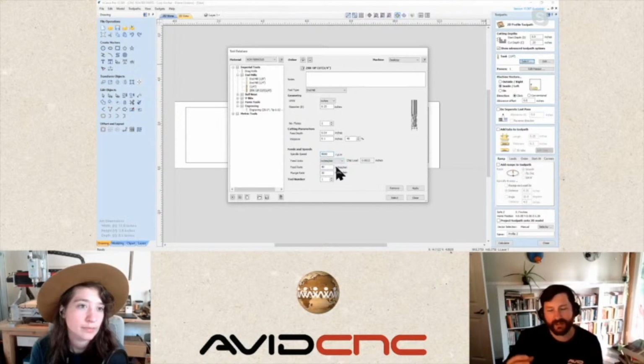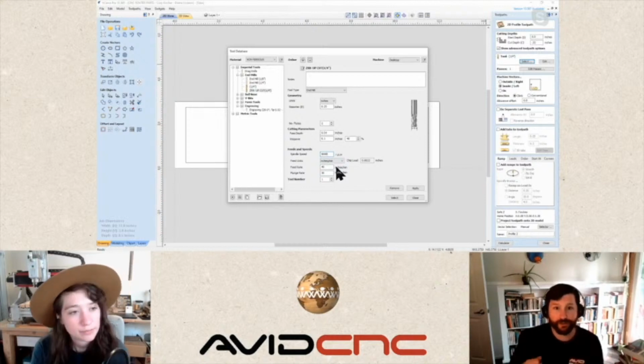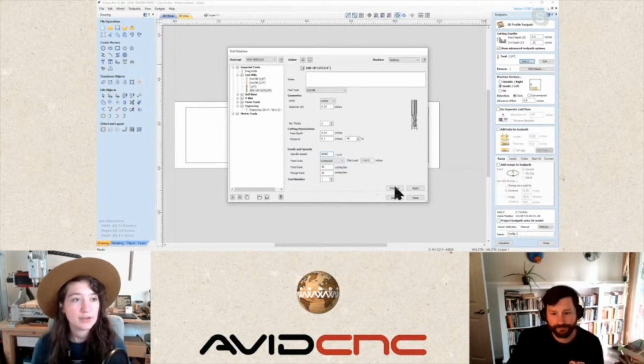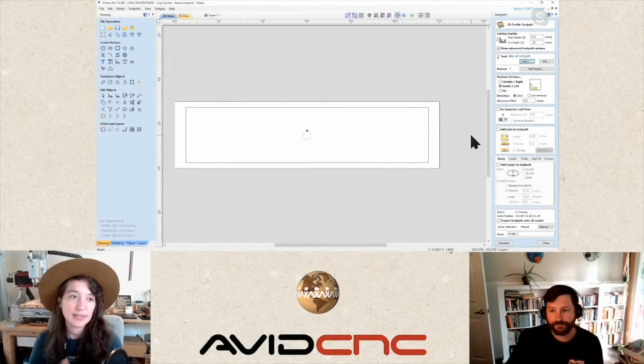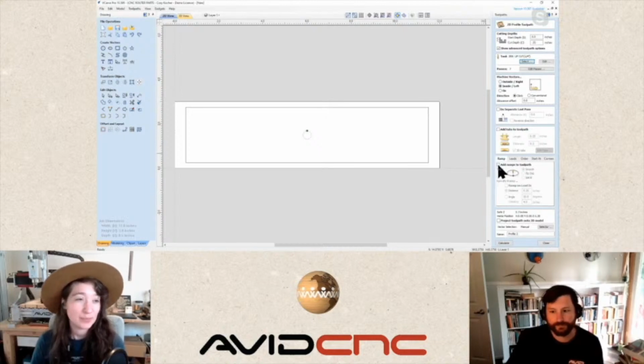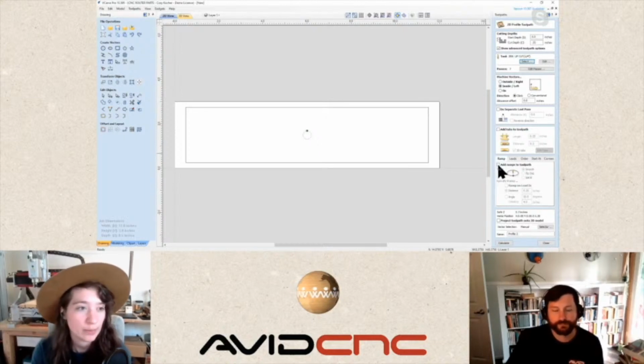And so that's going to be a more achievable feed and speed for this size vector, right, Sami? Yeah, definitely considering that the lateral movements, it's not going to be able to get up to that fast, and also to consider the type of chips that you're making and the heat distribution.